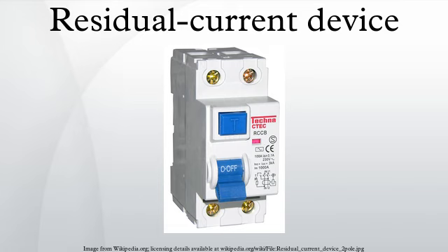Ground fault condition is defined as an unintentional, electrically conducting connection between an ungrounded conductor of an electrical circuit and the normally non-current carrying conductors, metallic enclosures, metallic raceways, metallic equipment, or earth.